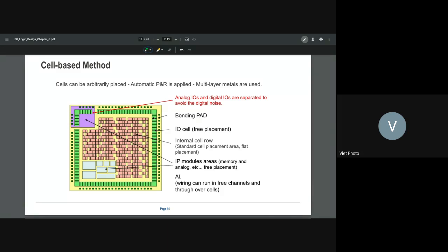First of all, the IO cell. Why do we need the IO cell here? Why don't we have the cell here go all the way out to the external world? We need the IO cell as the middleman, because the cell in here is driving between them. It's a very small cell, with very small parasitic capacitance and low resistance and so on. All the load in here is very small.